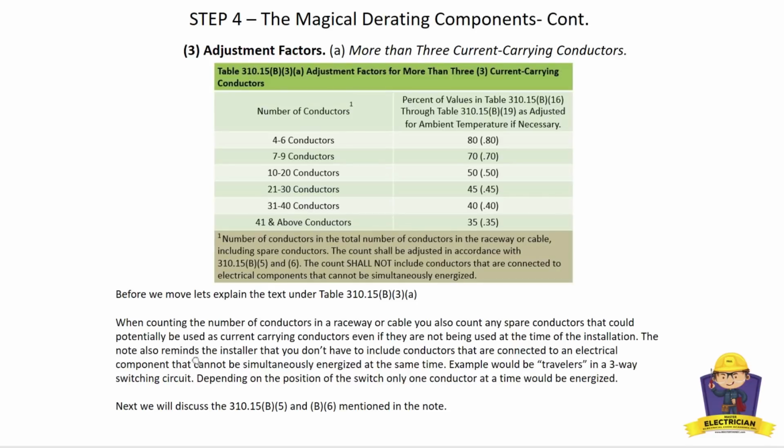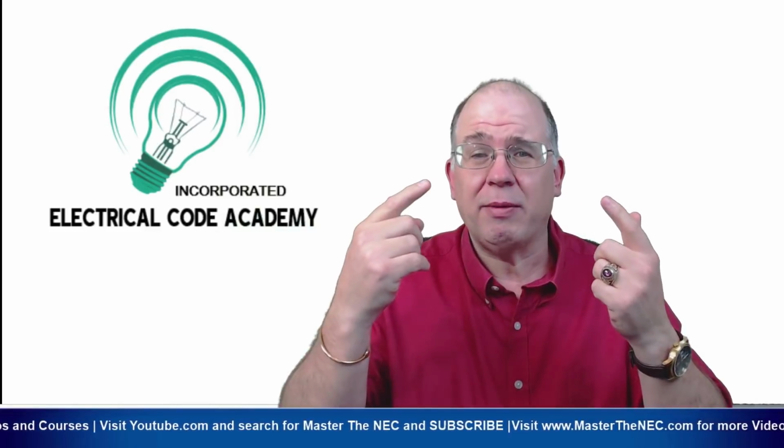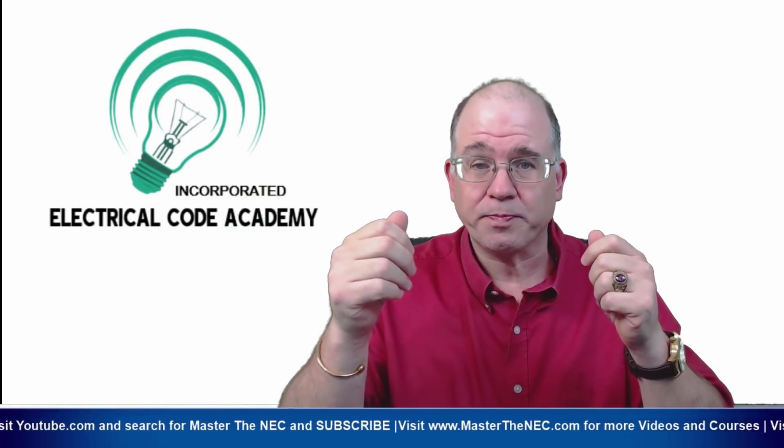Okay. Now, the note also reminds the installer that you don't have to include any conductors that are connected to electrical components that cannot be simultaneously energized at the same time. So what example would that be? Well, use a three-way switch is the easiest way. You have a common terminal and you have travel terminals. You want to turn on a luminaire from two locations.